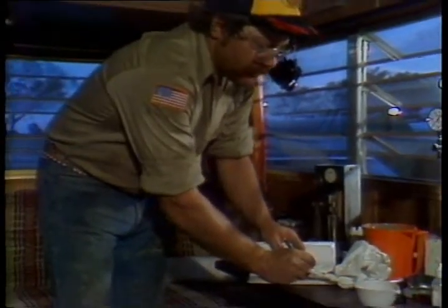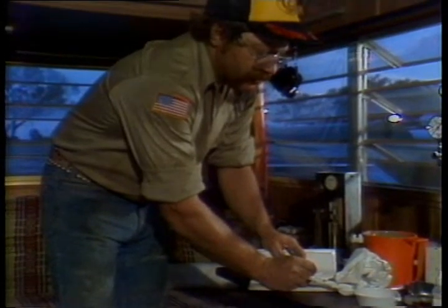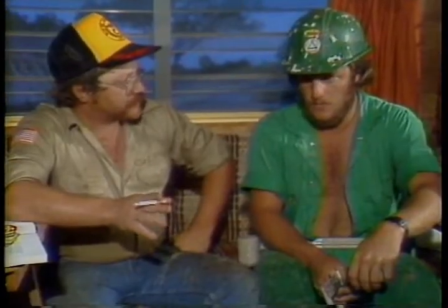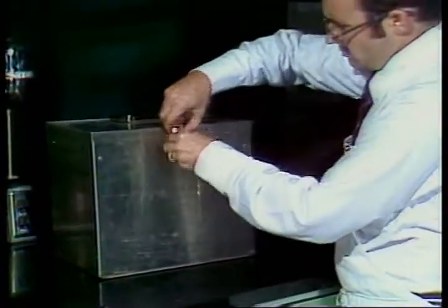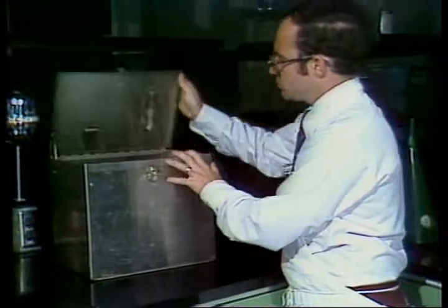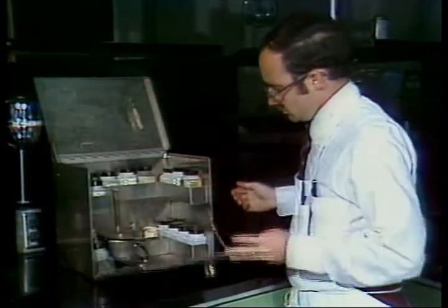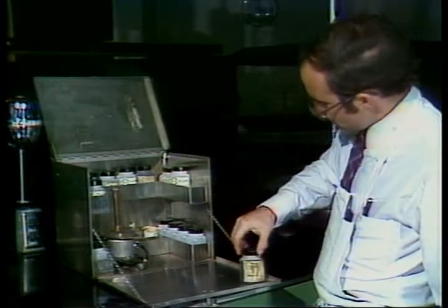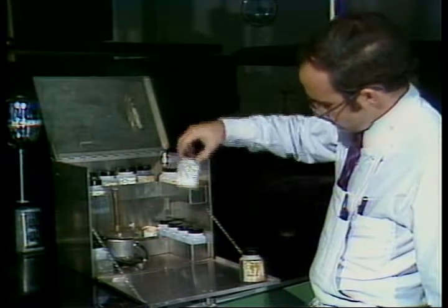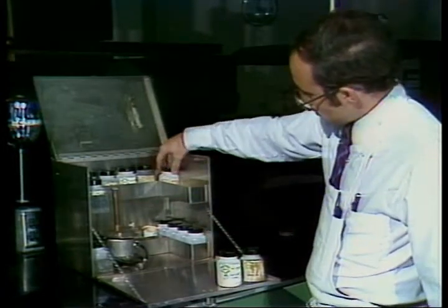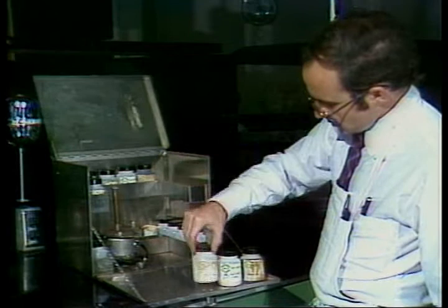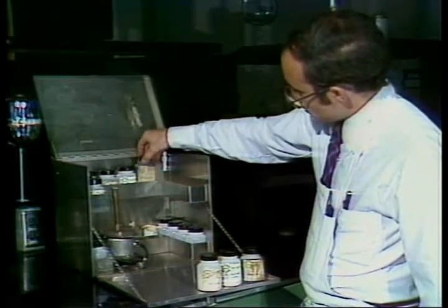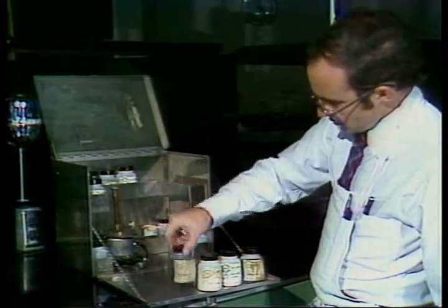Once the mud engineer's run all his tests, he'll have a pretty good idea as to what's going on with the mud downhole, and he'll be asking you to make adjustments in the mud from time to time. One final thing that is sort of a last resort, the mud engineer will probably have one of these kits. It's just a cabinet that contains samples of all the mud additives. If he runs into a problem that he can't figure out by using his tests, he'll start experimenting with a little of this and a lot of that until he finds a cure. So you might get into quite a few exotic additives from time to time.